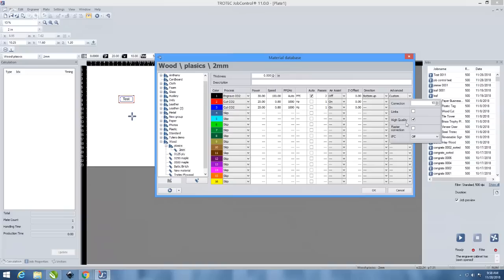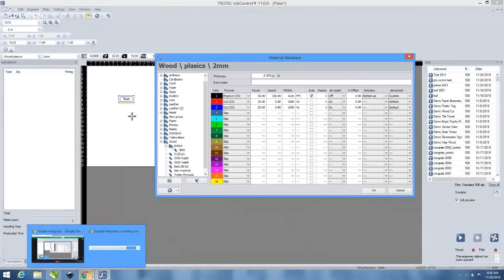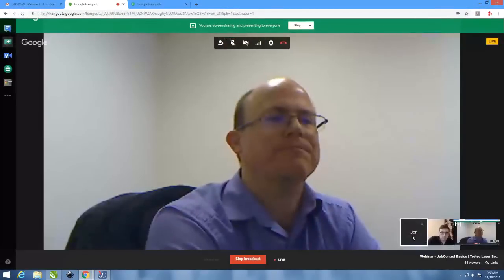And that's because the laser is moving only over that area. So it's engraving at a much, much slower speed than it is when it's hitting the rest of the word. So high quality mode basically forces the machine to engrave a full swipe, regardless of whether it's just a small little stick of an L or a Y there, or whether it's the full word. And because it's moving at a consistent speed over the entire word, it makes the quality very uniform and look very perfect overall.